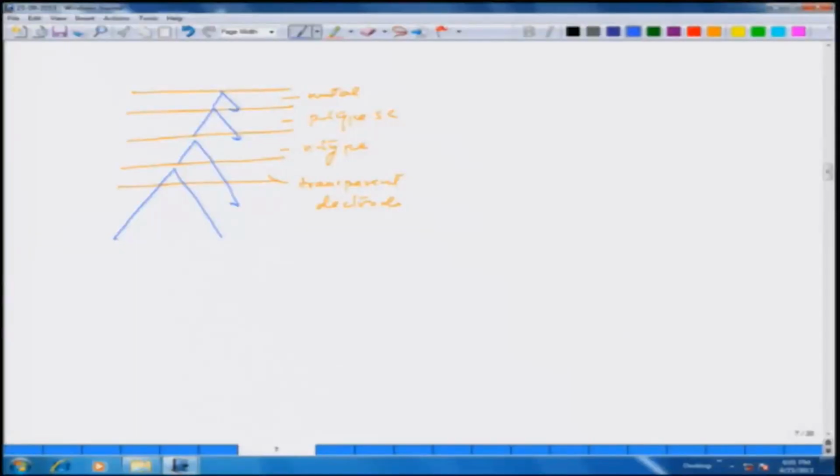A very important point that I want to mention here is about the angular behavior. This is just to highlight that even when we have a single interface, you saw that the optical performance of the interface is highly dependent on the angle at which light is coming. Even from daily experience, you may have noticed that with your LCD screens or some displays, you can see them only from a certain angle, and that is because when you have all these multilayer thin films, they are highly directional.